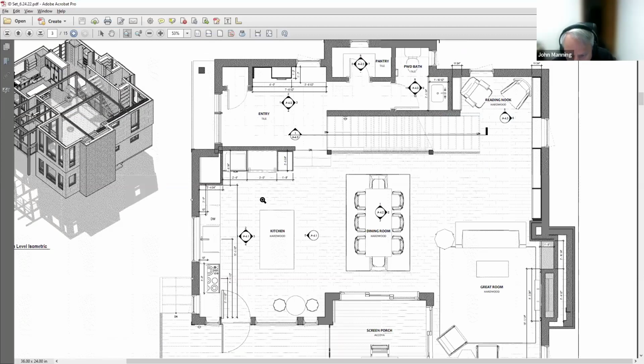Yeah, I'd have to look around for that photo, but I remember seeing it, these solid poured pillars, which I've never seen before. So that's the other shear wall by the kitchen. That was actually also poured solid concrete, because it was really the only way our masonry contractor could pour that. There was no way to get formwork inside of the rectangle at that location. So that is a solid 2-story concrete shear wall.